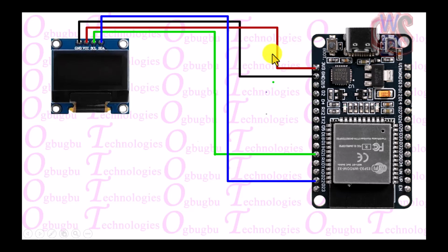But nevertheless, what I'm saying is for those who will be using this with Arduino in the future, always connect the power VCC of this OLED to 3.3 volts. This is because this OLED display is able to power itself from 3 volts to 5 volts, but for security reasons, in order for you not to damage this board, always power it with 3.3 volts. We have 3.3 volts also on all your Arduino dev boards, so this is not an issue. But if you are using an external power to power all this, you can use a step down to regulate these voltages. So that is for that.